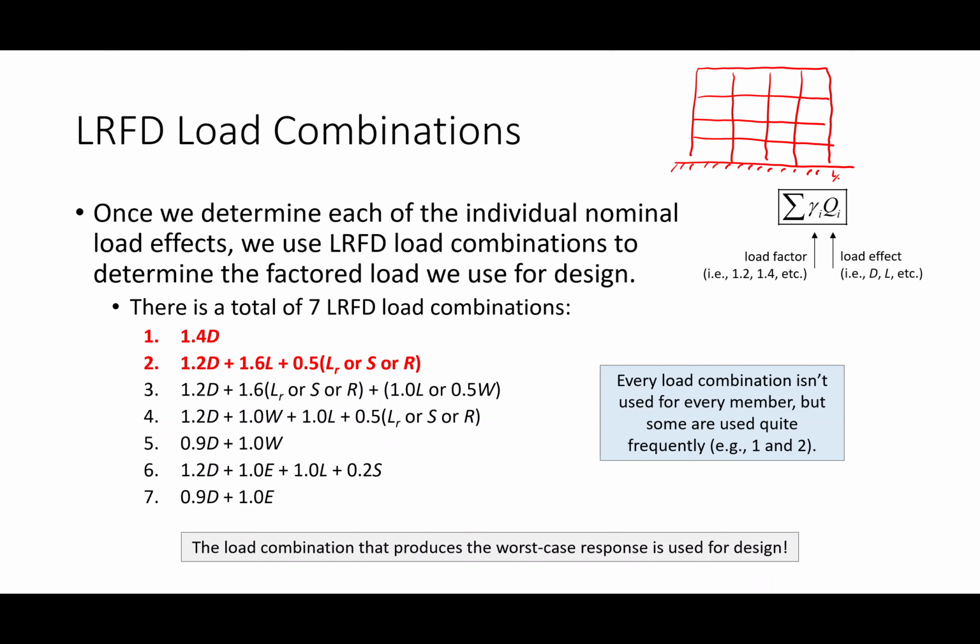Let's say that the building experiences a lot of wind. If the building is exposed to wind, the building is going to want to topple over. We don't like buildings to topple over. So a simple way of arresting that is to maybe pick a bay and install some braces.